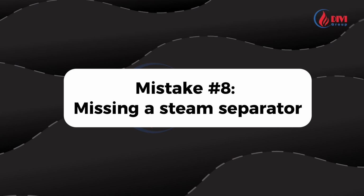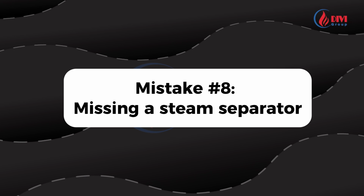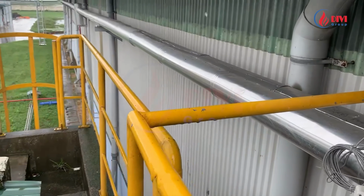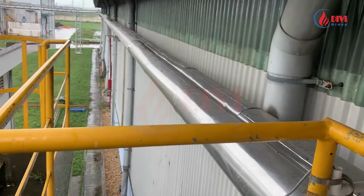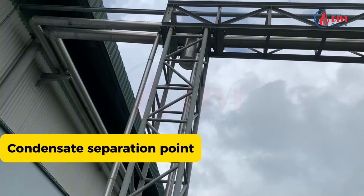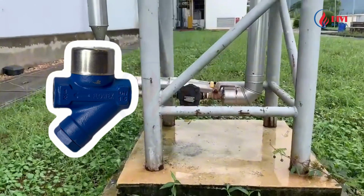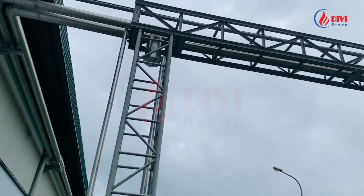Mistake number 8, no condensate separators on the main steam line. Many factories have hundreds of meters of pipe without a single separator. Steam loses heat as it travels and condenses. Every 30 to 50 meters, install a condensate separator and trap station. Condensate should be routed back to the boiler.